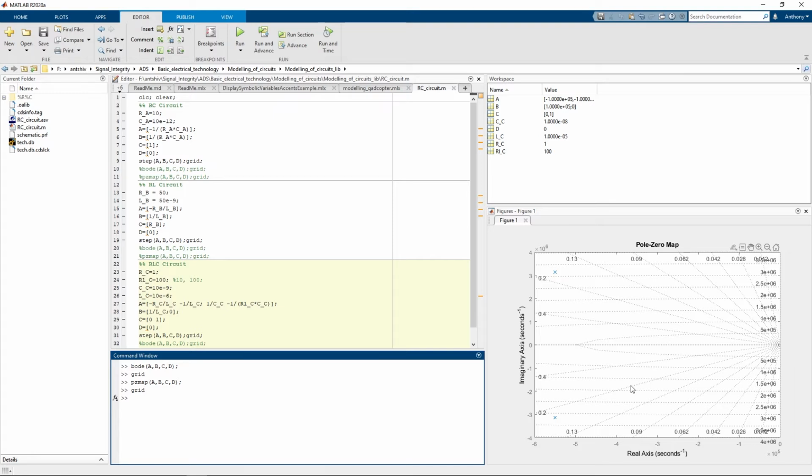So you'll always have a left-hand side pole zero. And in this particular case, if it's not on the x-axis, that means you have complex poles. This shows that it's a dynamic system, that there's some oscillation. And that's how you interpret this pole zero map over here.